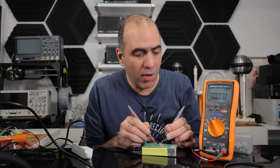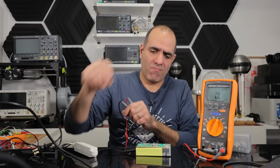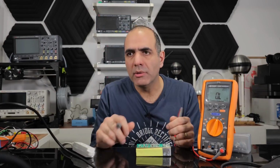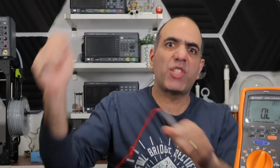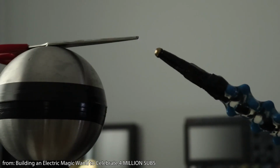For some reason the supply voltage to the chip is 0. I wonder. Look, the chip supply line is shorted to ground, which means the control chip is broken. It didn't die a natural bulging death, you know. This was my raising desk's power adapter and died while I was swinging my high voltage magic wand around. Some good size arcs jump from this thing, eh?